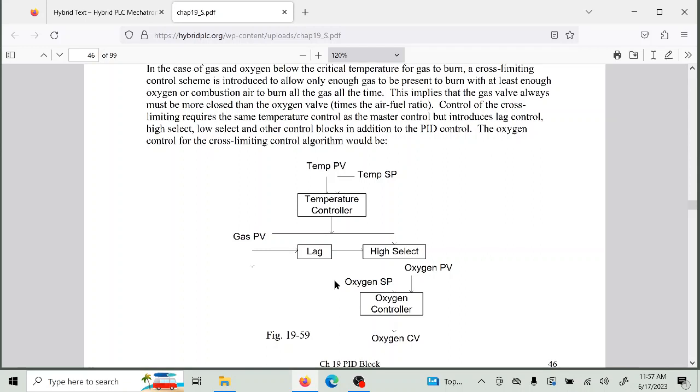If you're going 9.2, well, you're a little bit off, but not much. 9.2 is not bad. 9.3 is you're a little lean on the natural gas, so you don't burn quite as efficiently. The more lean you get, the less efficient you get. The more air you're putting through, you don't need.